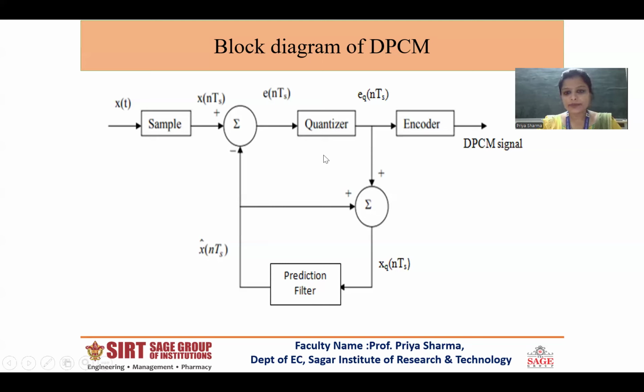So this is the encoding part of the DPCM signal, where each sample is compared with the previous sample for its quantization to be positive or negative. Now coming to the decoder part, each received signal is converted back to an analog signal by a digital to analog converter after the serial to parallel converter, is stored, and then summed with the next sample received. This operation is similar to the accumulator used in the transmitter. The integration is performed on the analog signals, although it could also be performed digitally.